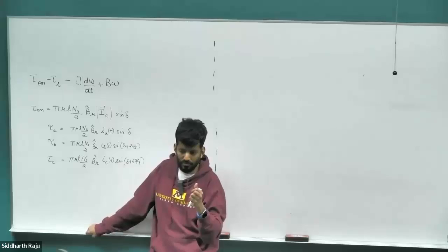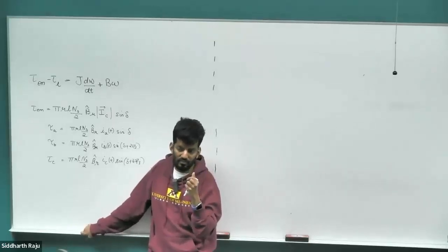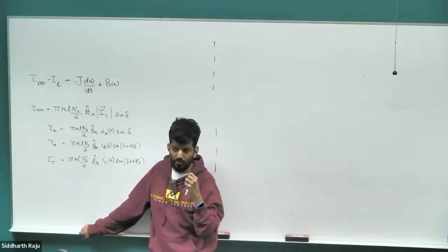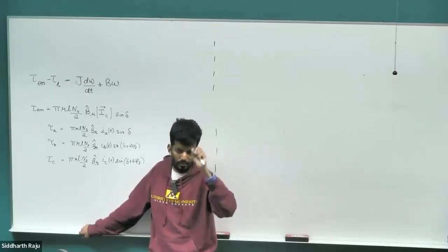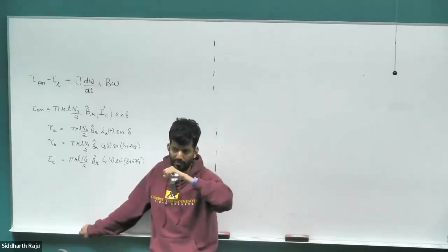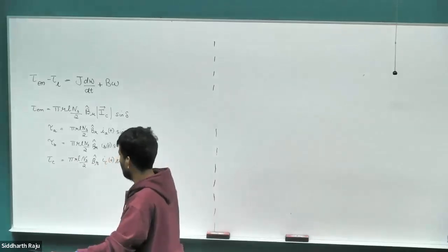If those two are not the same, then we saw the net torque would be 0. If they are changing at the same speed, then there will be a torque produced, but the torque would have a highly oscillatory component to it, which is what makes a one-phase permanent magnet synchronous motor very inefficient. Once you get a one-phase permanent magnet motor rotating, it can continue to provide sustained torque, but it will be an oscillatory torque. There is an average DC component and also an oscillatory component, which makes it very noisy and very inefficient, and it will damage the battery quite easily.